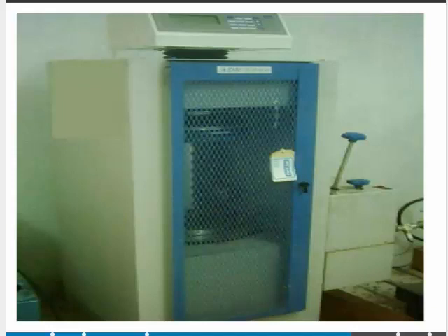Align the specimen carefully on the base plate of the machine. Rotate the movable portion gently by hand so that it touches the top surface of the specimen. Apply the load gradually, as I have told you, at the rate of 140 kg per centimeter square per minute till the specimen fails. Record the maximum load. Now when we have placed the concrete cube in this compression testing machine, record the maximum load and note any unusual features in the type of failure.